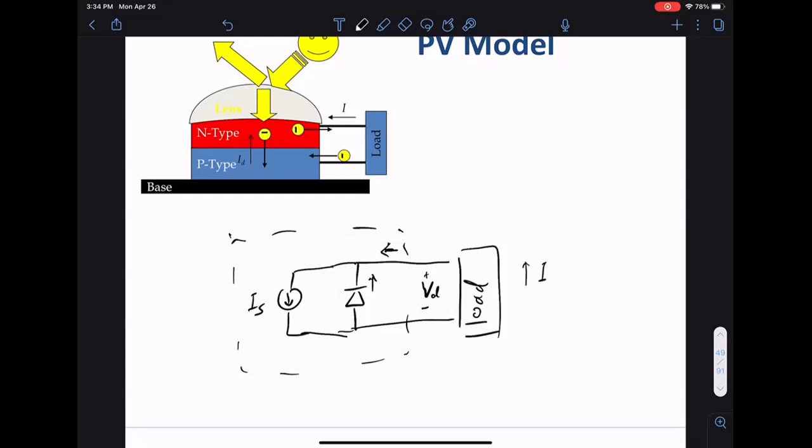Right, so there's a reason for that. If you look at the N and p-type, the question is more basic. Let's say you just stack two of them together. Why don't the electrons just rebalance across the two? One has excess electrons, one has a reduced number of electrons, one has an excess number of holes. Why don't they just hop across and rebalance on their own? Obviously they don't do that, otherwise you wouldn't have a diode left over. But the reason is between the two materials, you have a field that opposes the electrons from moving from one type of material to the other type.